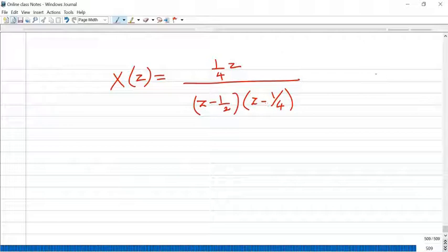Okay. So we have the formula a power n u of n, whose z transform result is z divided by z minus a. For that purpose, like DTFT, while finding inverse DTFT, what I told you, we always keep 1 e power j omega on the left side of the denominator. Here also I am keeping 1 z here, so that at last I can multiply this z on the right side and I'll get the formula z divided by z minus a format.